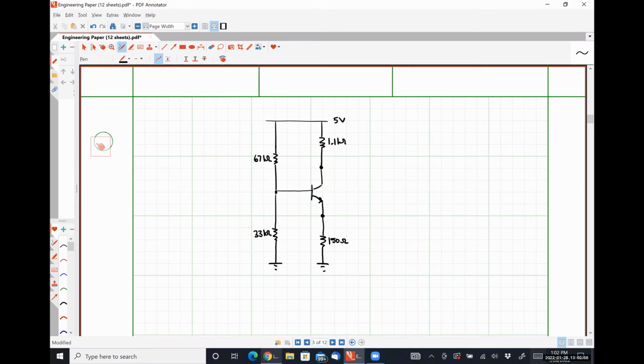So this is our DC portion of the circuit. Typically speaking, we would couple an input signal through a coupling capacitor that I'm going to call CC1, and we are going to assume that CC1 is very, very large. Okay.